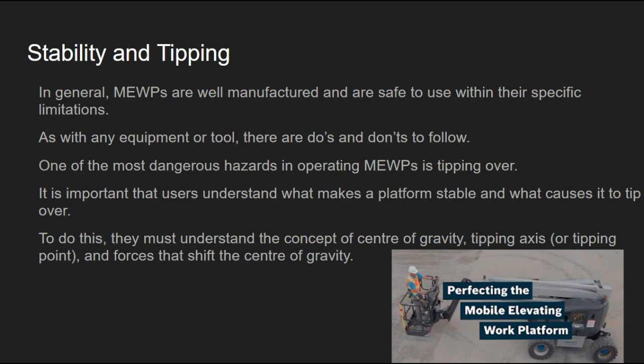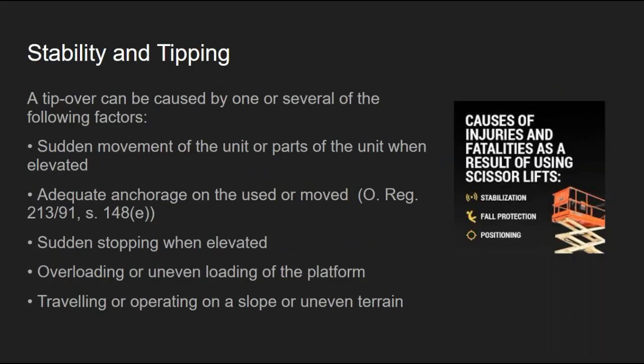To do this, you must understand the concept of the center of gravity, tipping axis or tipping point, and forces that shift the center of gravity. A tip can be caused by one or several of the following factors: sudden movement of the unit or parts of the unit when elevated, inadequate anchorage on the unit used or moved, sudden stopping when elevated, overloading or uneven loading of the platform, and traveling or operating on a slope or uneven terrain.